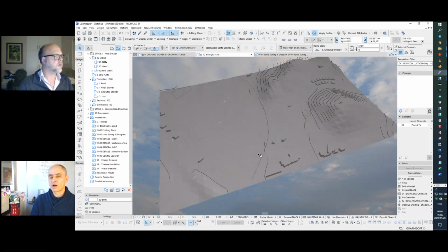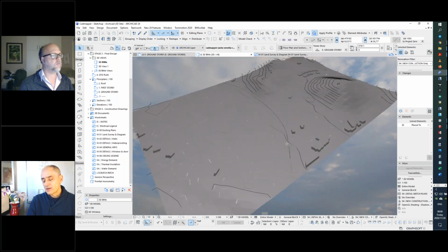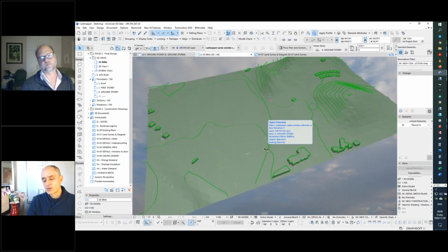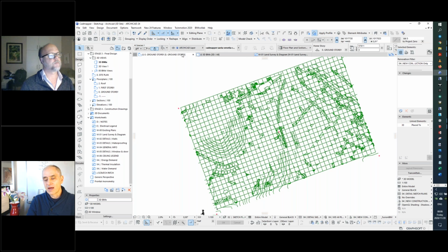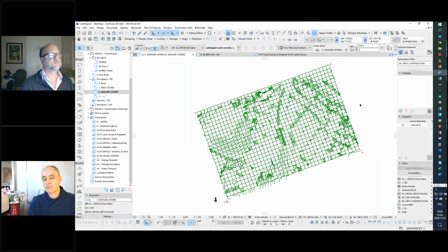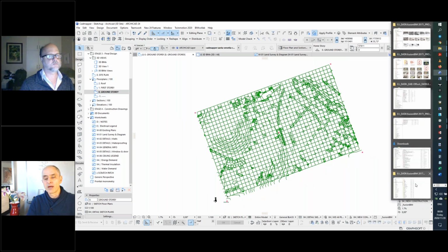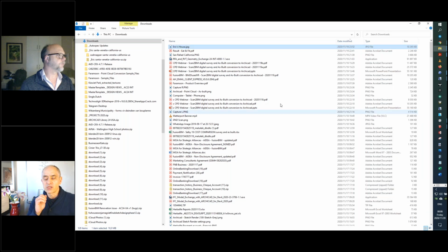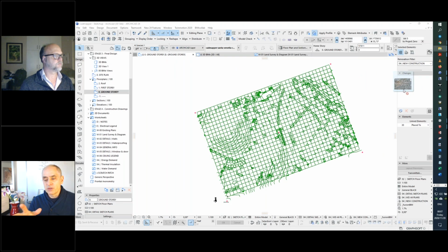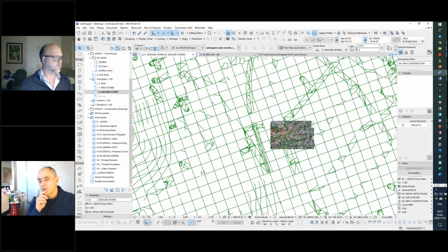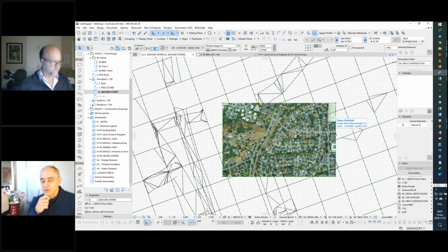What I would suggest probably would work is to take the picture and place it just as a graphic on the plan and stretch it as a picture on plan to match whatever the terrain is, because once you place that picture and you get it sized, then you can do a measure. Since this SketchUp import should be in scale, then if you get the picture in 2D to match, then you know the size of your texture map. So we can see that picture right now came in at a certain size, so you just have to make it a lot bigger.